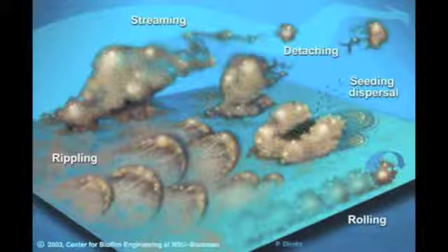Genetic engineering efforts consist of improving strains and chemotactic ability, using mixed population biofilms, and optimizing physicochemical conditions. Gene expression in biofilm cells differs from planktonic stage expression, and these differentially expressed genes regulate biofilm formation and development. Biofilms are especially suitable for the treatment of recalcitrant compounds because of their high microbial biomass and the ability to immobilize compounds.